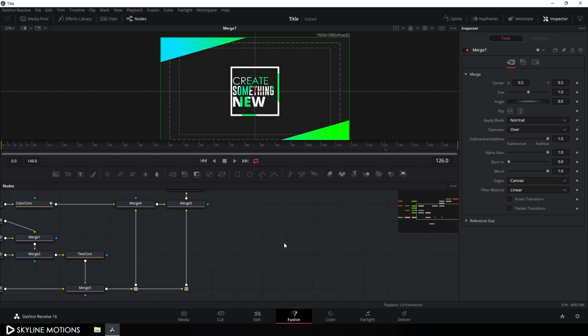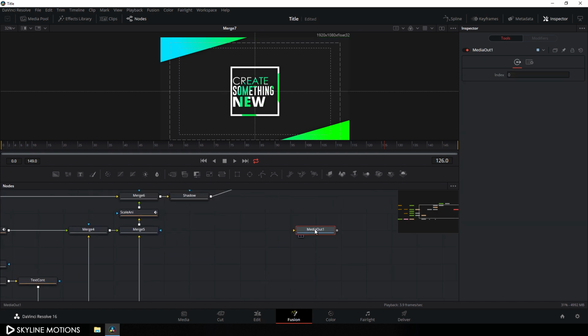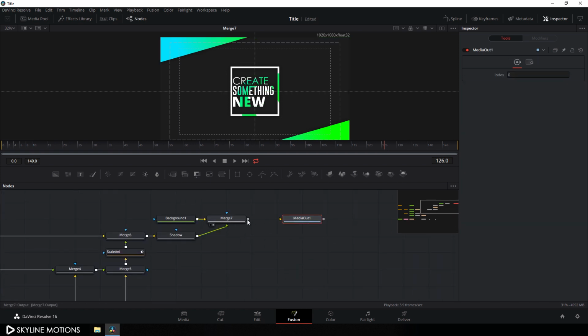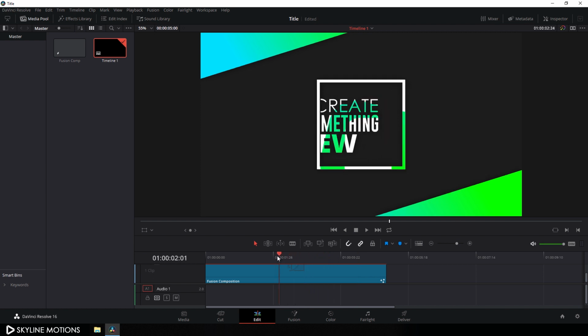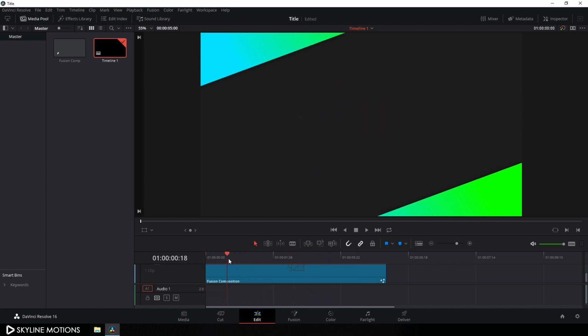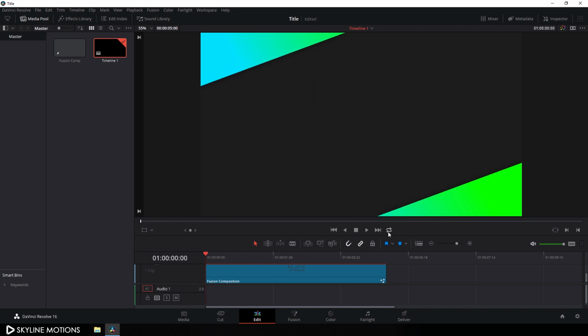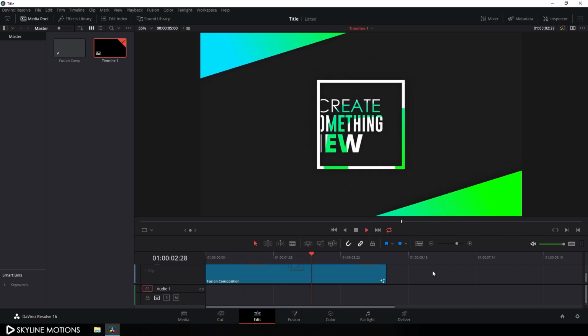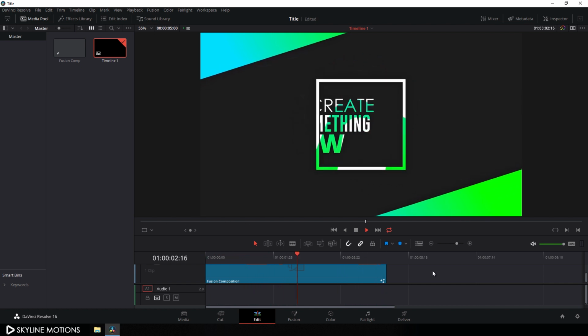And finally we have to connect media out with our main output. So just connect this media out with this merge 7 like this and then go to your edit tab, and as you can see our text animation is ready for render. So go to the very beginning of this animation and click on this loop button and let's play this animation. All right, so it's looking nice, and that's all for this tutorial guys.